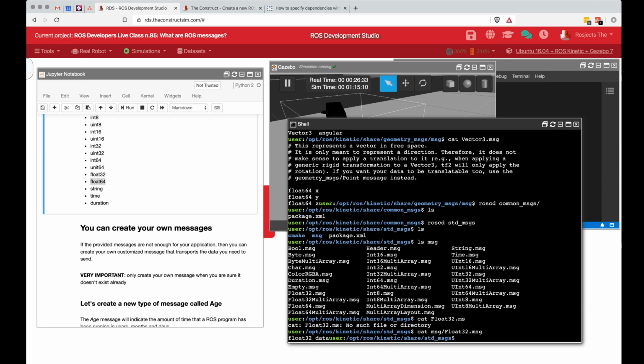This callback function is going to capture all the published data in the odometry topic. And once you have captured it, you receive the message as a Python data structure, and then it's very easy to get into the data of a message.